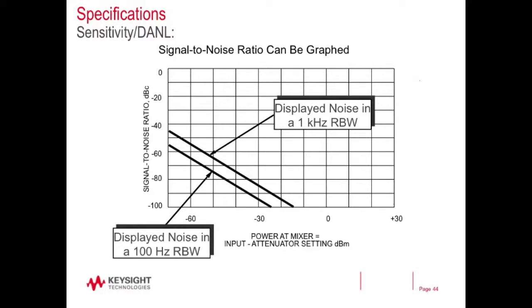That represents a roughly minus 125 dBm per hertz noise floor, okay? So I'll be able to see something along those lines. If you go up here, because we have a different resolution bandwidth, this is minus 60, and you come down here, and that's roughly minus 55, so that's minus 115.